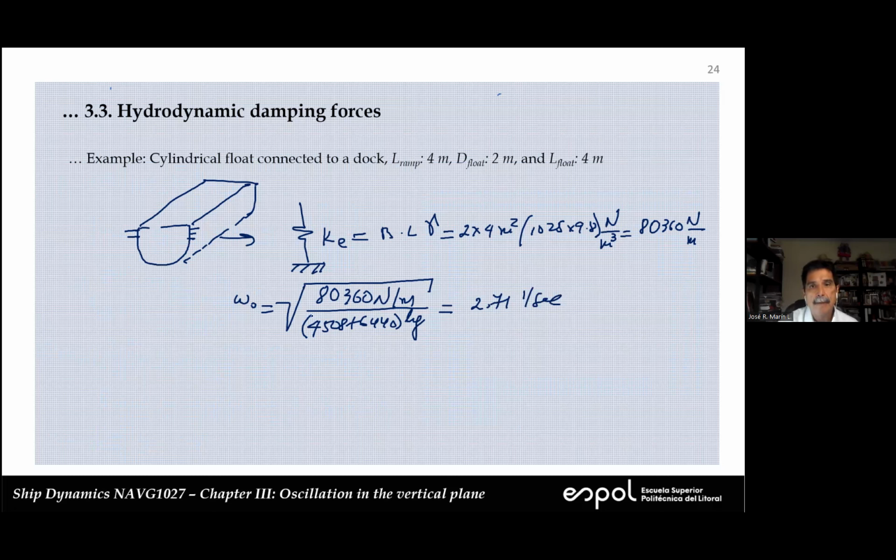So this is an approximation using the assumed value for the frequency. So we have to do a check. Okay, so we calculate omega 0 squared B over 2G. So it's going to be 2.71, the value that we have calculated, squared, times 2, that's the mean, 2 times G. Okay, so that's non-dimensional, and the value is 0.75.